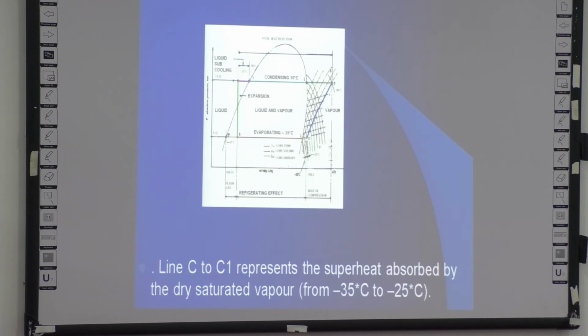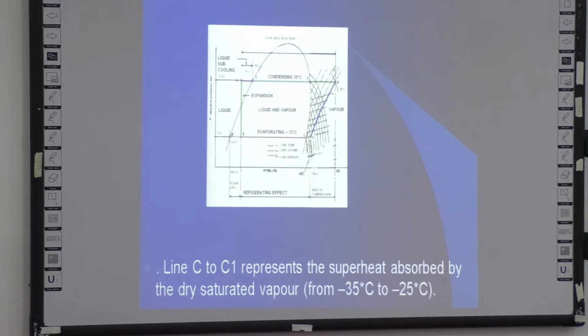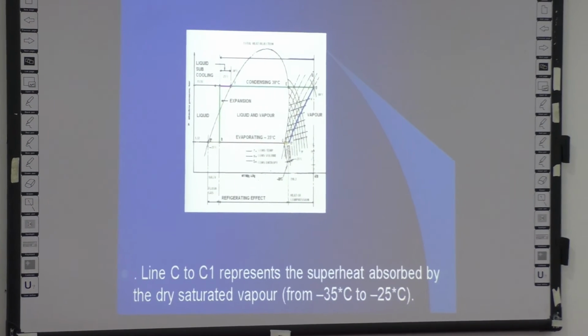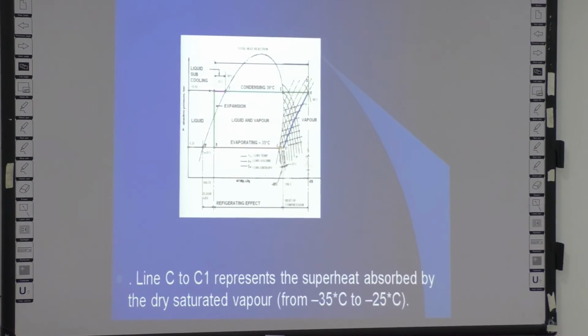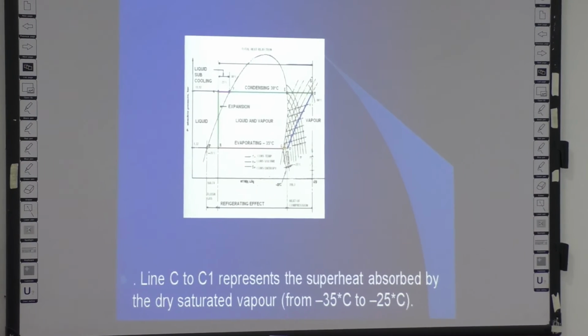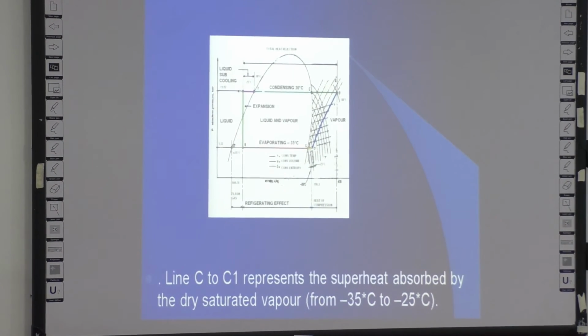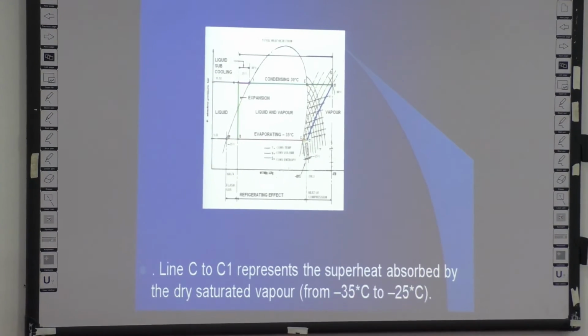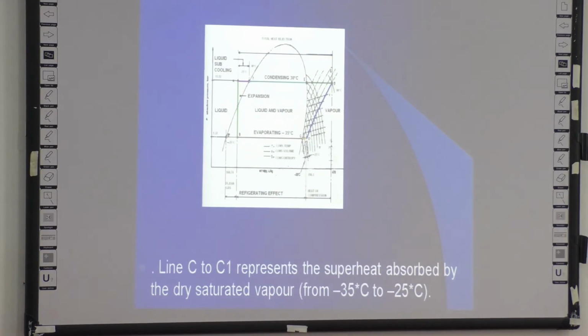So the next stage of the curve is where pressure starts increasing like this, and you can see that the enthalpy is also increasing until it reaches the outlet of the compressor, from where at constant pressure it goes into the condenser.